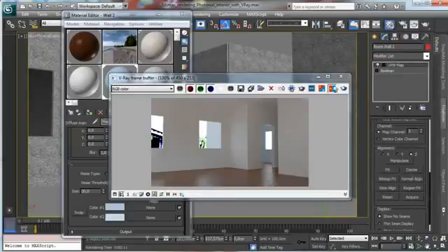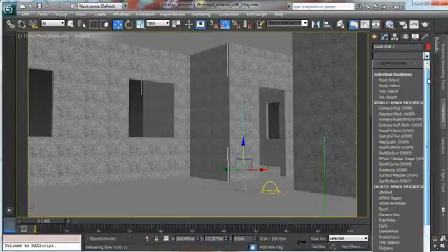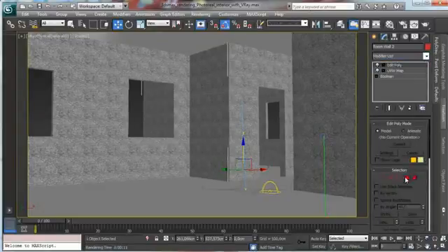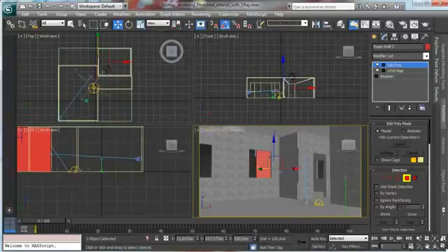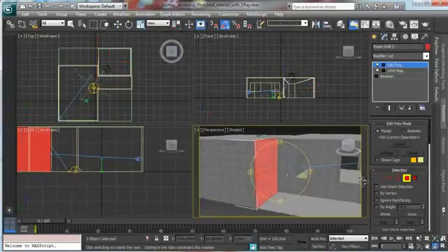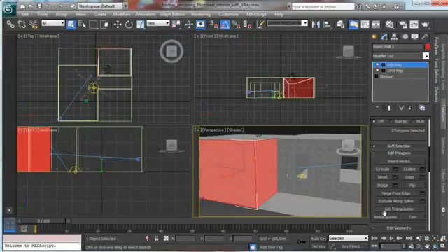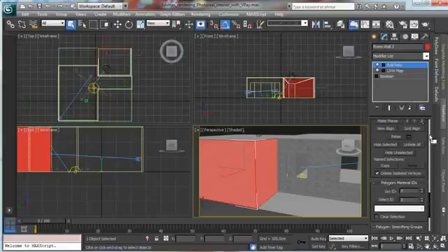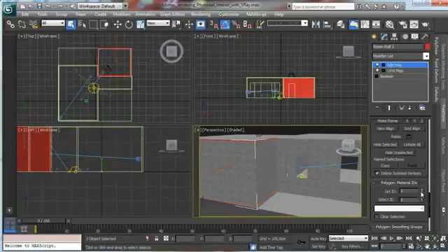It is nice. Okay, so I'd like to change the outside of the wall there. Let's pick this model, and with an Edit Poly, select this face, but we have to change the other one also. So let's go in perspective, and we have to change this one and this one to a different ID. So the ID is set to 2, and with Edit, Select Invert, we have 1.